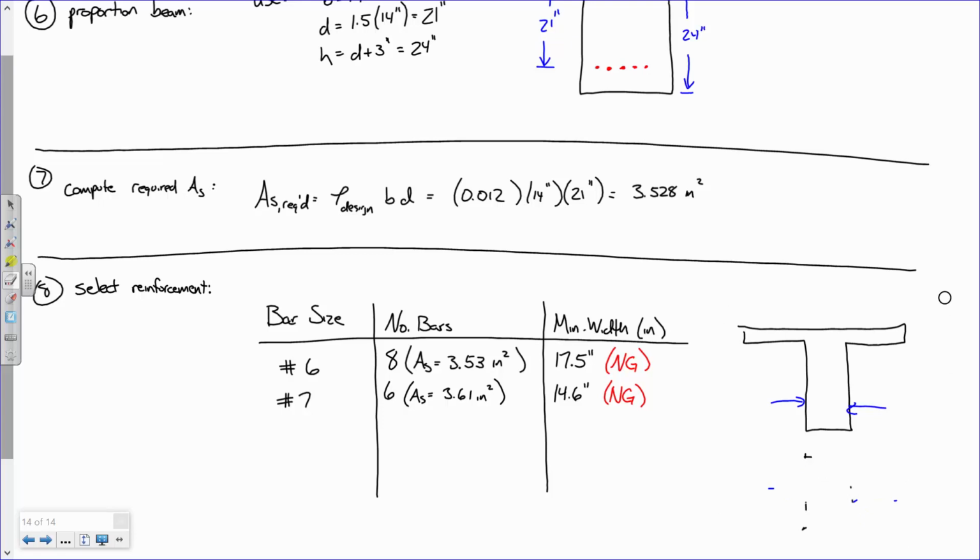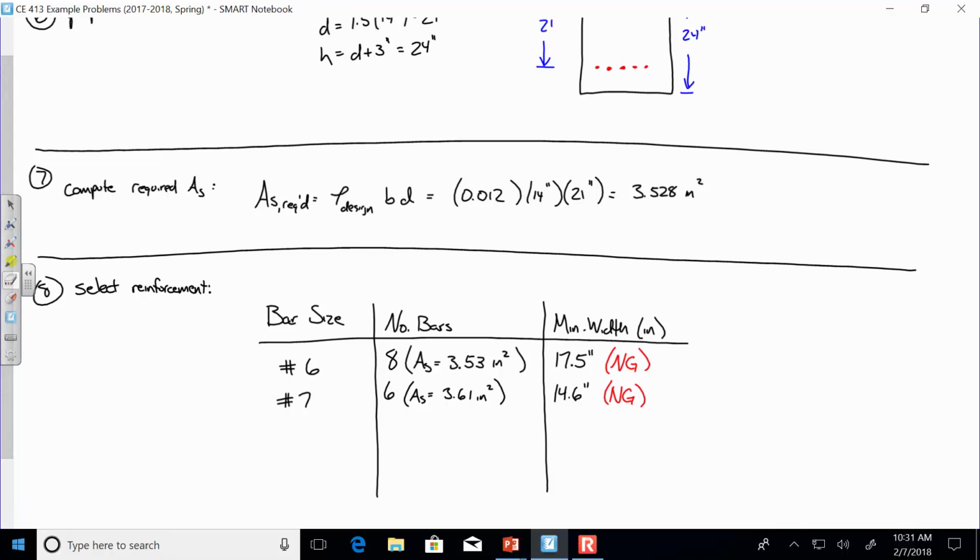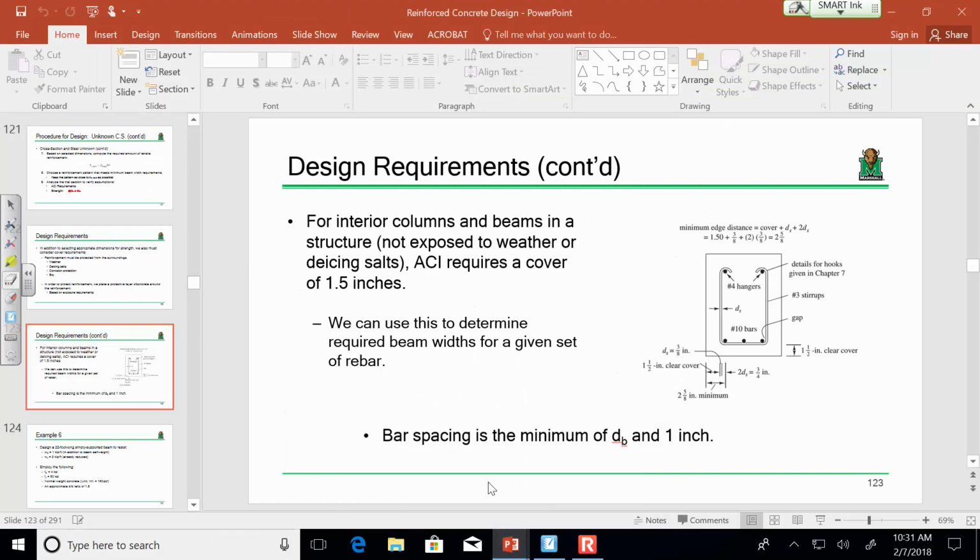What's the stirrup again? Okay, the stirrup is this little U-shaped thing inside the middle of the beam. We use stirrups to tie the rebar together, but also to resist shear. We're going to do shear later. So for now, unless otherwise noted, just assume number 3. If you're using number 4 stirrups, you got some serious shear going on. Not saying that isn't something we'll consider down the line, but number 3s are very common. Like a holder for the rebar. For now, that's basically all you need to assume. It's just tying all the rebar together.